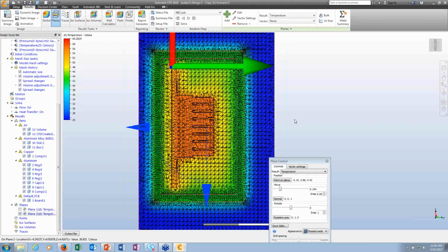When you're going through solids, it's just conduction. The material properties of aluminum here are not changing based on temperature. So you really can get away with a pretty coarse mesh through the metal fins. So it's just a waste of resources, and I would prefer to do it in CAD.